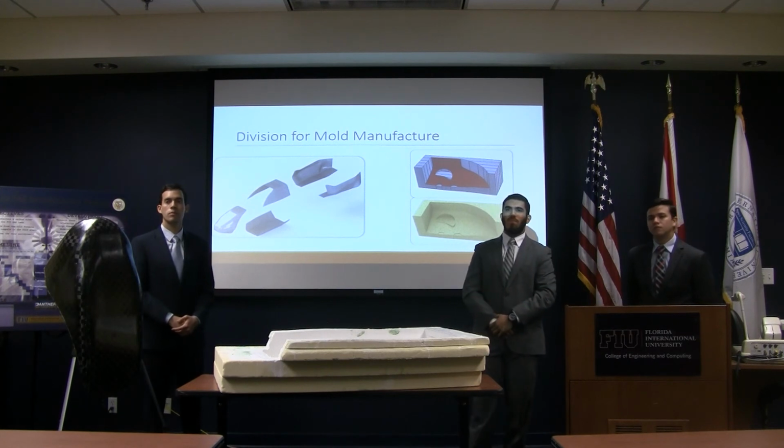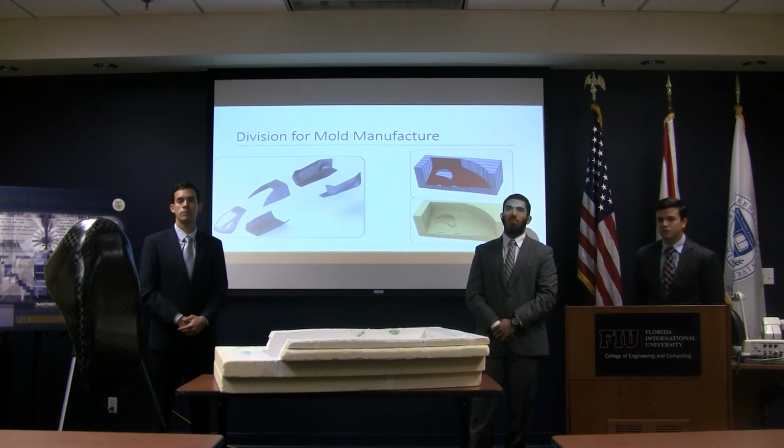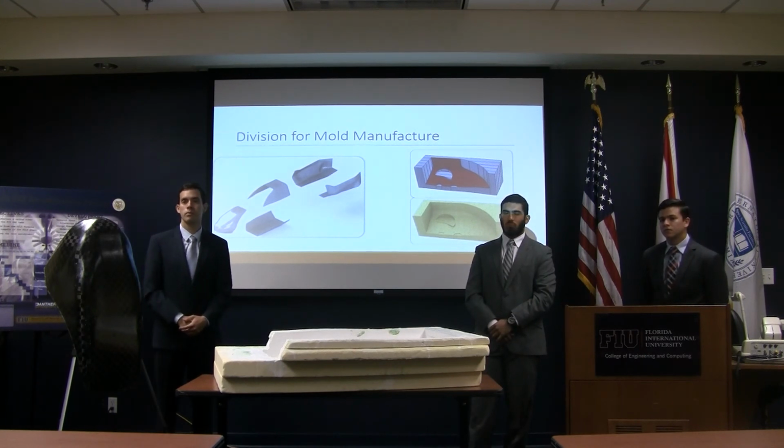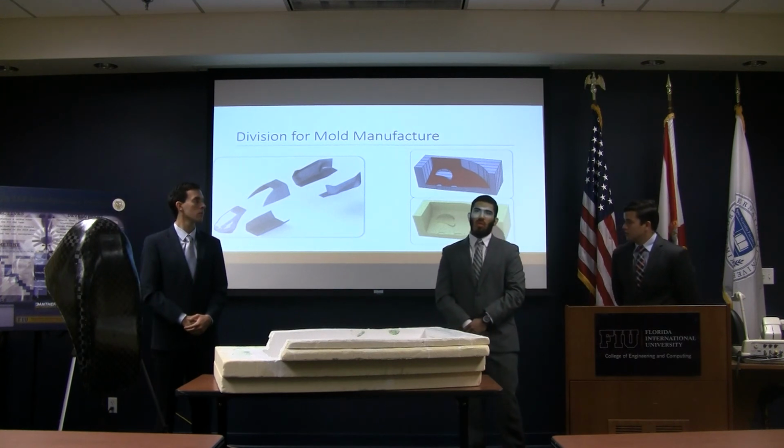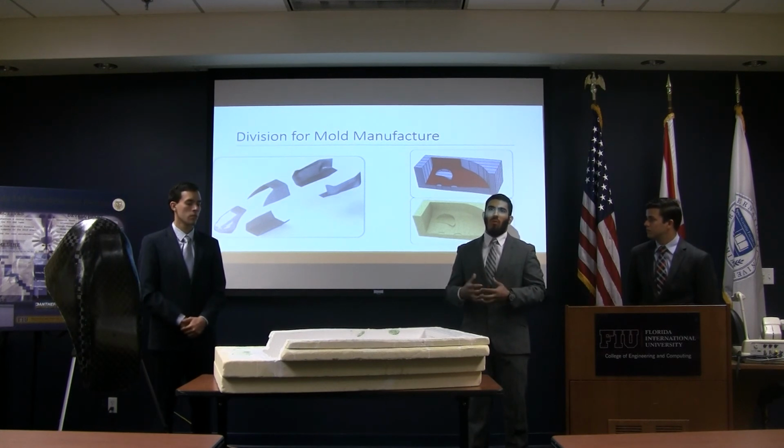And my second one was, I saw in your report you guys used the water tunnel testing to give yourselves an idea on a scaled model. Did you do any similitude for taking into account the difference between the scaling and the fluid difference when you moved from a scaled model in a water tunnel to what would be a full scale in air? We did. The main parameter that needs to be correlated between those two, especially since we're using different fluids, is the Reynolds number of the flow. So we did take that into account. However, results for the water tunnel testing were pretty inconclusive.